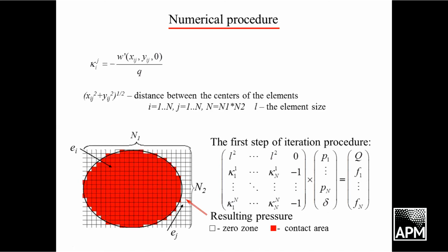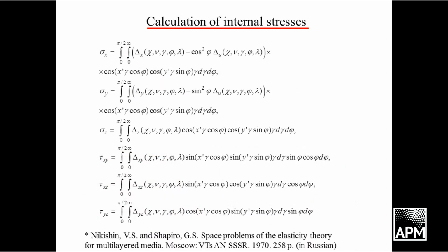And here I should say that if we calculate stresses, then we can calculate for this problem only stresses inside the layer or inside the half space. We can calculate stresses inside rigid bodies, inside the plate or inside rigid half space.